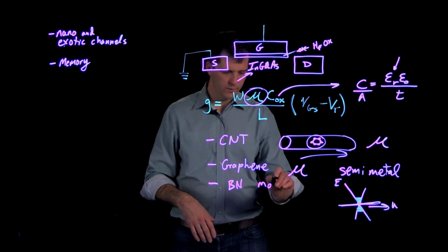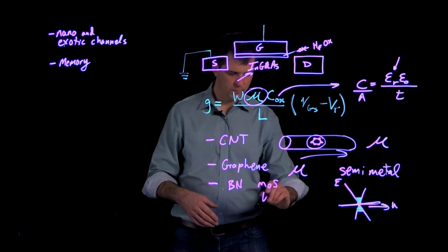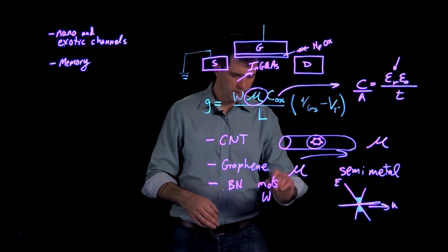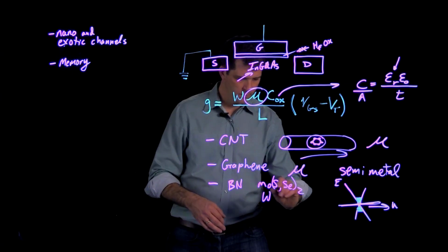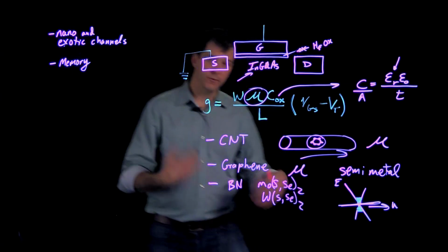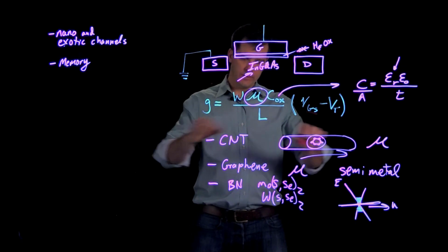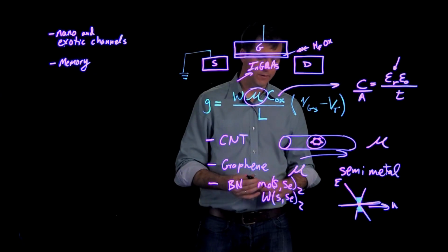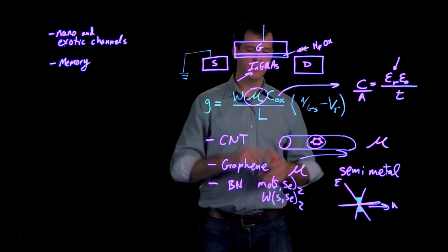So recently, some nice transistors have come from the molybdenum or tungsten chalcogenides, meaning sulfur and selenium bonded to this metal. And these form pseudo two-dimensional structures, sort of like sheets of atoms that are a little bit thicker than the case of graphene, but they do have a band gap and thus can be gated on and off, just like silicon.